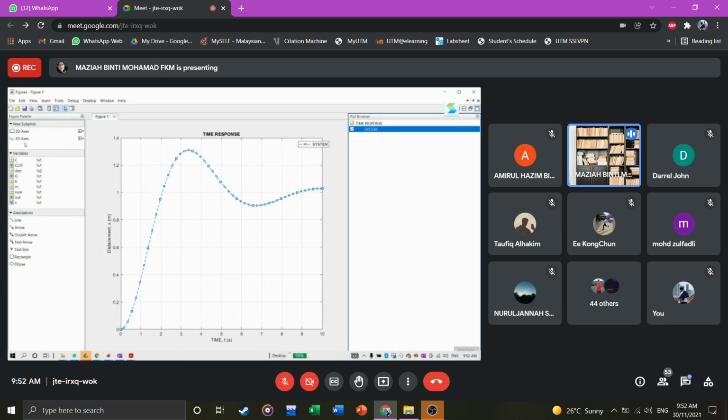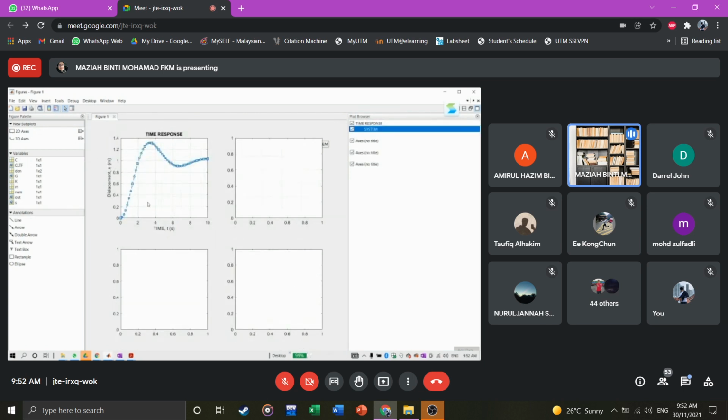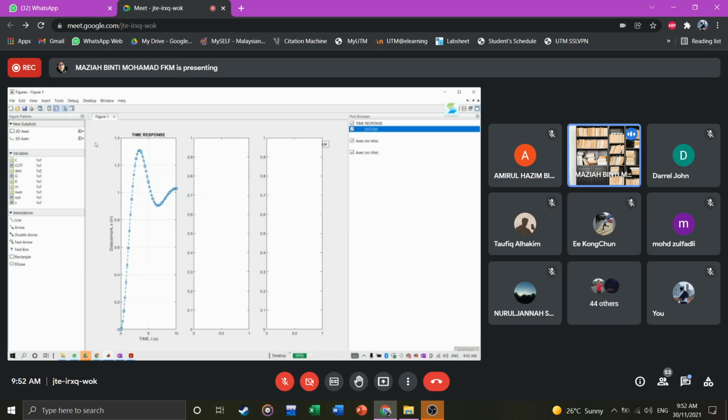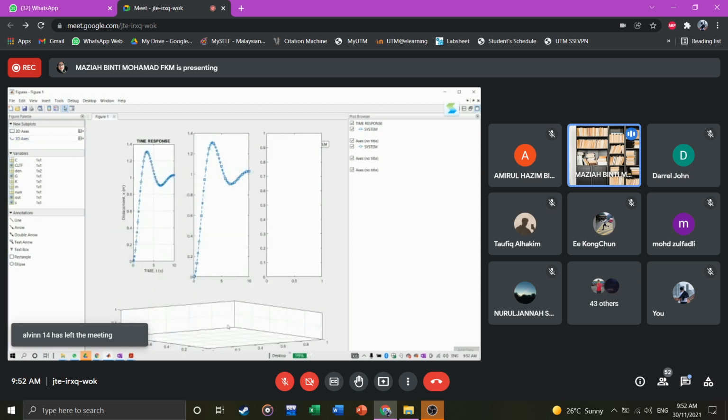Okay, so in figure palette, if you need to add another plot, you can arrange that, for example to put 4 plots in one diagram. Okay, you can change the arrangement there. Basically you can copy and then paste here. Okay, you can add a 3D plot.